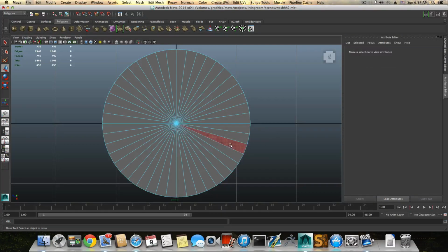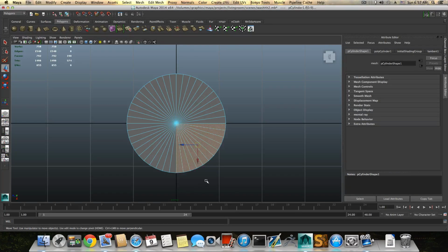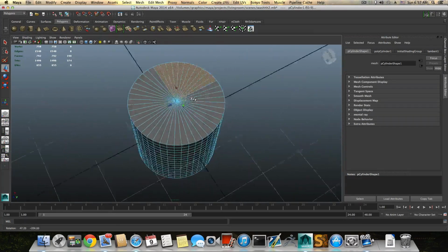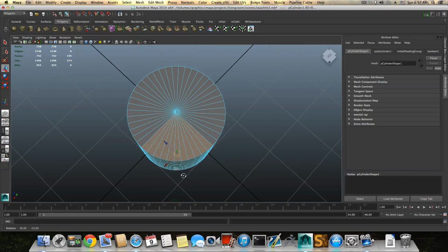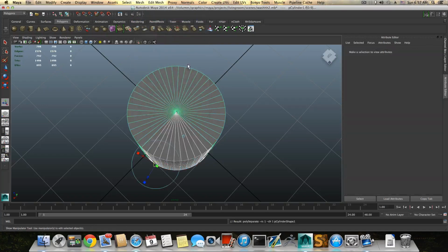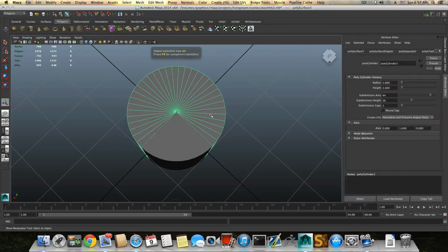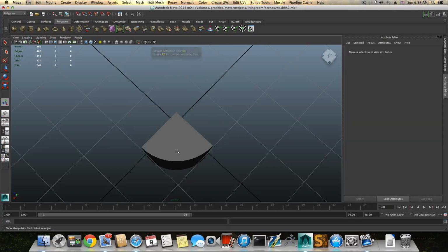Now there is a reason why I chose to add 44 subdivision axes. You see I have a line here, a line to this thick line of the grid, and a line here. So I'm going to select only a quarter of this whole figure, okay, and go over mesh, extract, and press F8 once or twice, 3 times, and delete this figure.